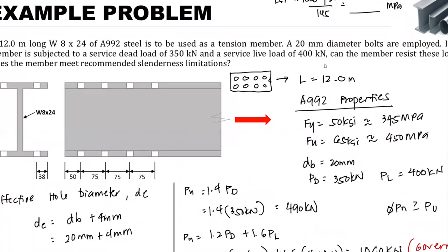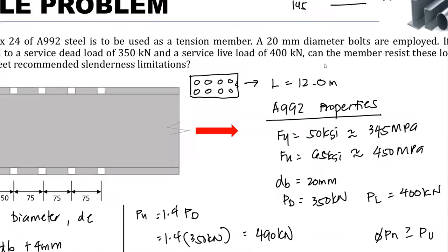If we want to identify which bolt will rupture first when tension rupture happens, we can imagine that we are facing the break line and we use a flashlight, and whichever bolts are hit by the light are our assumed location of fracture.